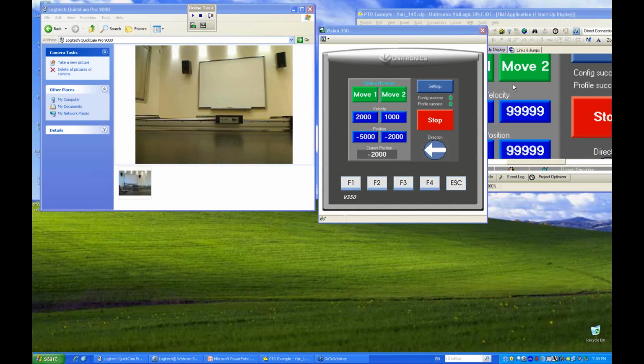You can connect the encoder, you can check the speed we receive from the encoder. You can also check the position, and you can do two things. First of all, for example, you can set a PID loop, and then the output of the PID loop can go to the speed.